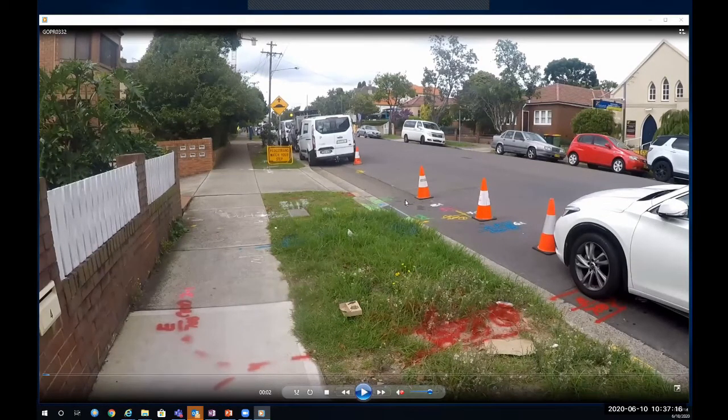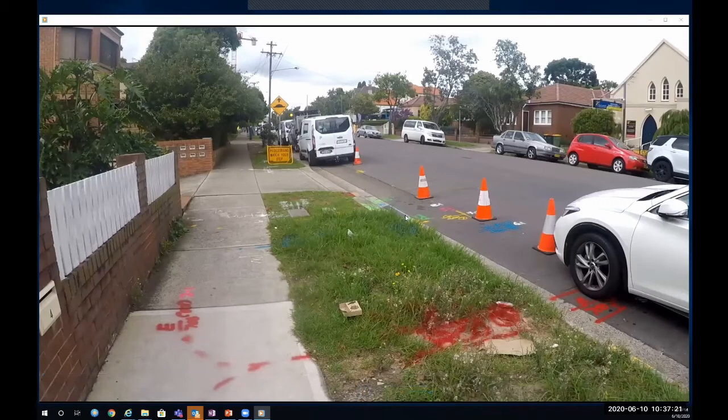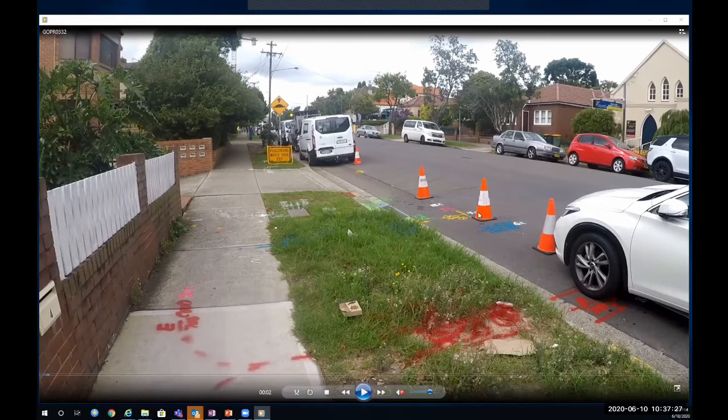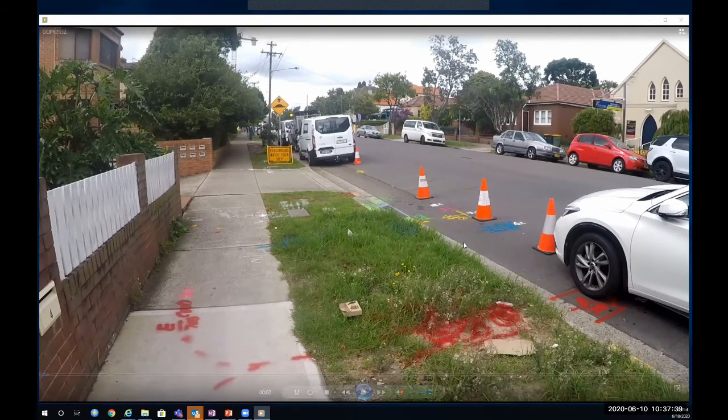You see some objects here. Traditionally, after they did this, they would go in with a total station and capture all these points, geo-referencing them, then capture the lines and put it on the map. What they do now, the people who do the ground penetration radar use a video.